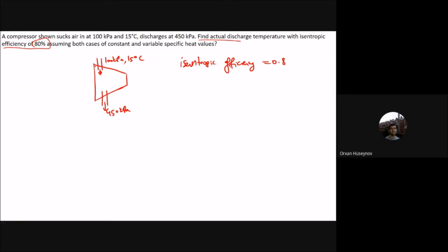first we select the control volume. Control volume is the air inside the system here. So I can write the first law, which says that the in should be the same as out. And for inlet, you will have the mass flow rate, which carries some enthalpy. And since this compressor needs some power, electric power, which will be work in, that one should be equal to the mass flow rate and the enthalpy out. These are out quantities. Okay. This is the conservation of energy.